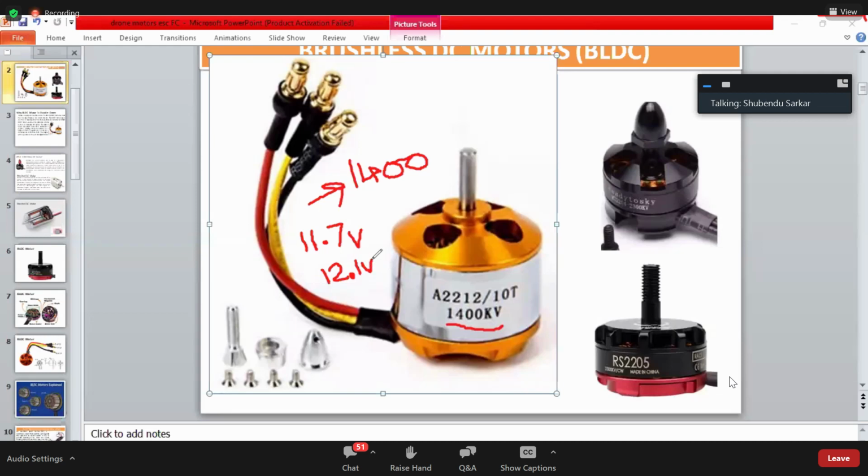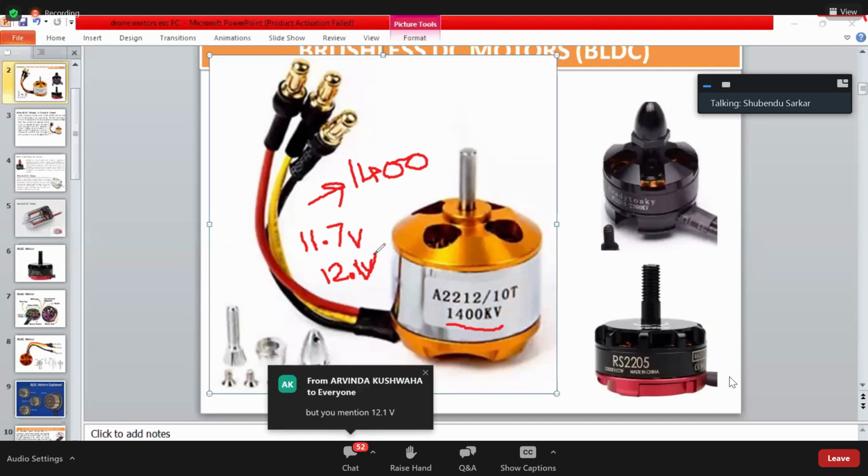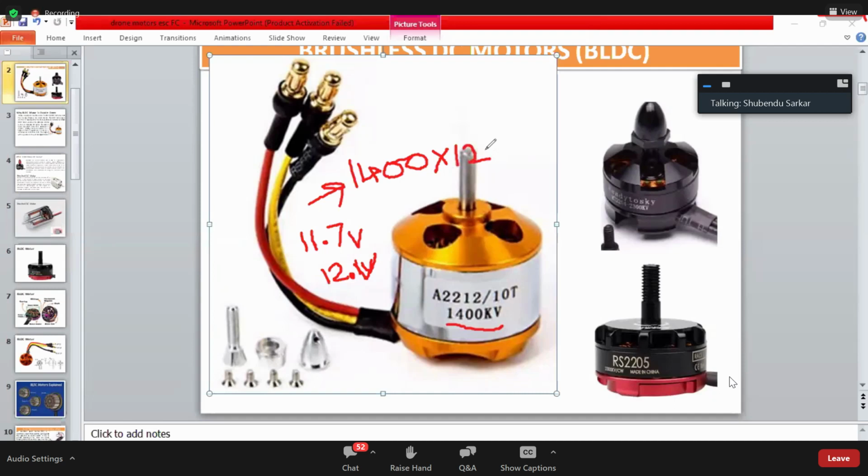So if I say we have a motor with a 1400 kV rating, and we put a 12 volt power supply into it, then it will give you 16,800 RPM. If you multiply this value by 12 volt, you get around 16,800. Similarly, if the kV rating of the motor is high, the RPM of the motor is going to increase with the voltage.